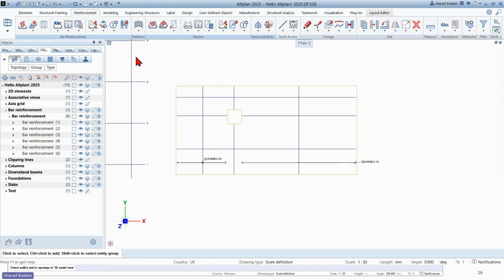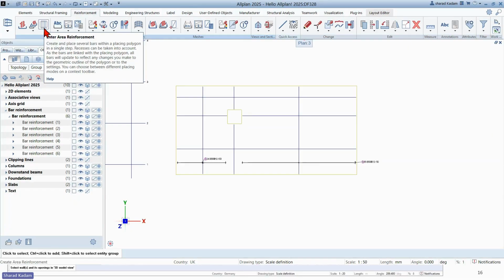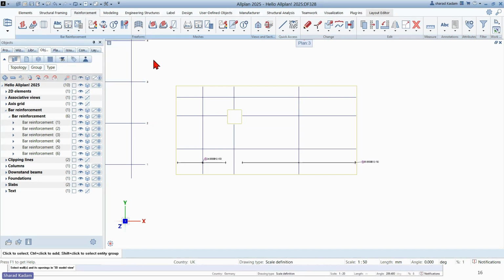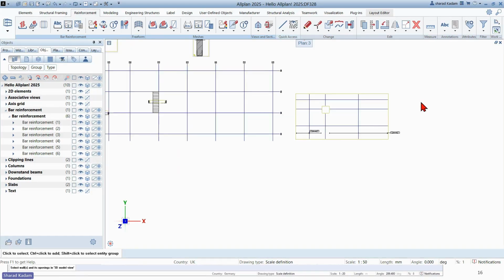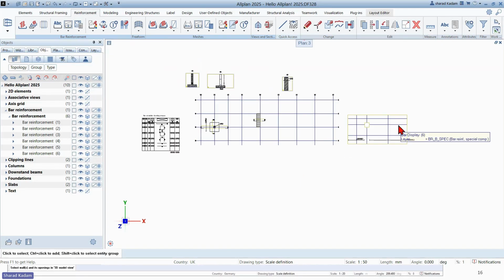So again, moving on to this, this is basically an automatic placement of reinforcements, or we call it an area reinforcement method. First we have seen the manual method, then this is slightly automated, wherein we can do the complete area in one go. We also have a method which is by using Python parts. So Python parts is a real good tool wherein we have a complete database, whether we have wall panels, hollow core, or column, beam, stairs, any kind of element, we can add the rebars to it.